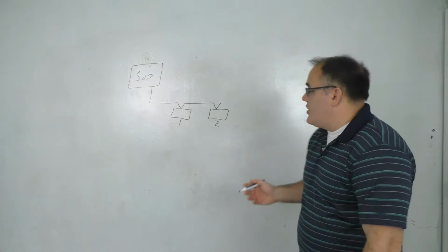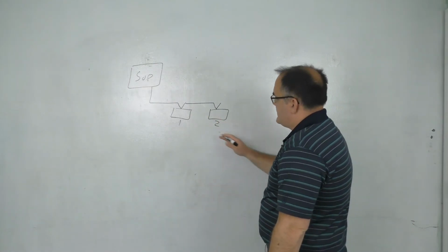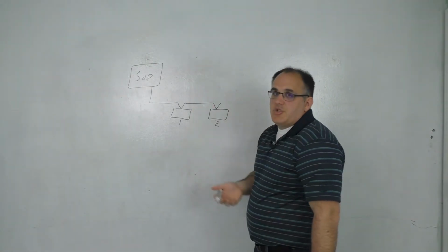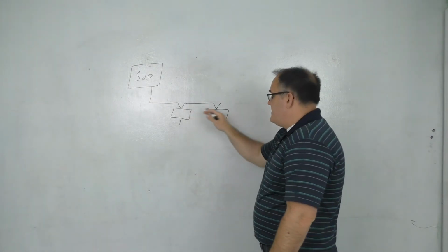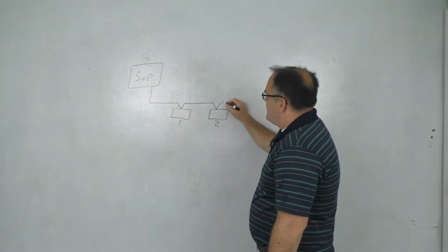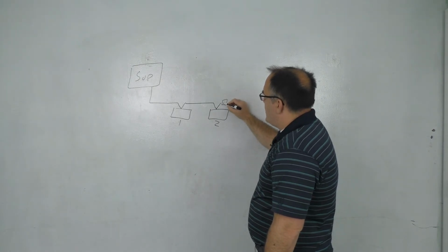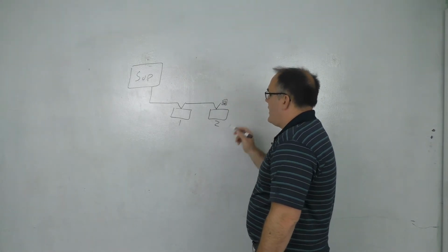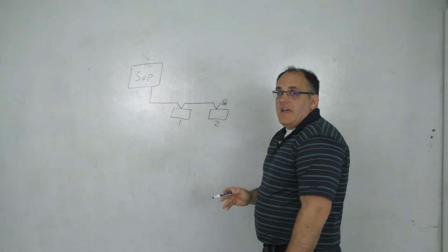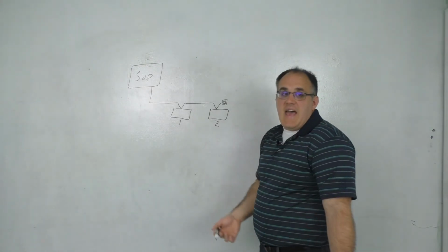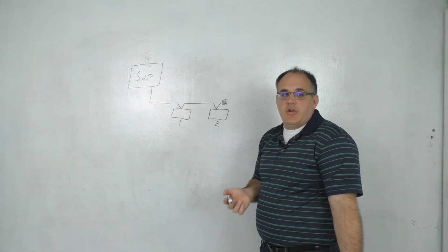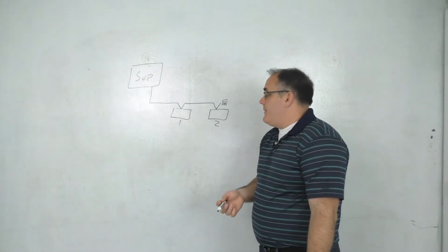So with that being said, our devices are laid out, they're addressed, we've got the trunk speed, we've got the network, we're laying out our wires properly, maintaining polarity, and then we come to the end and we put our EOL, our end of line, on. Now, let's say you go to an existing job and it's got something like this and you need to add a BACnet MSTP controller. How do you go about doing that?